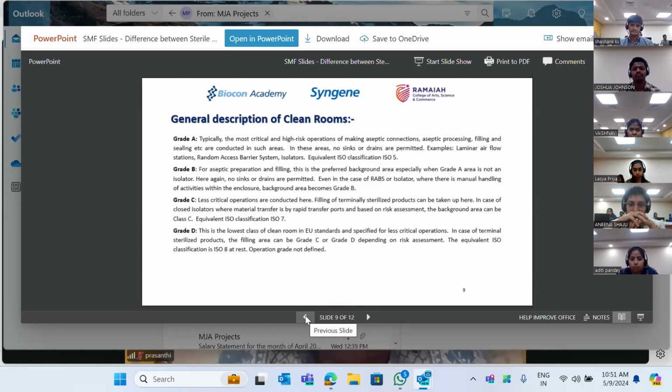Okay. Now, let me talk to you about what the area classifications are for carrying out aseptic manufacturing. That will give you a differential with respect to the area classification for sterile manufacturing. In aseptic manufacturing, areas are classified according to the risk levels of cleanliness and microbial contamination. The classification is typically based on international standards like ISO 14644 for clean rooms and associated controlled environments, like what we talked about in the first lecture.